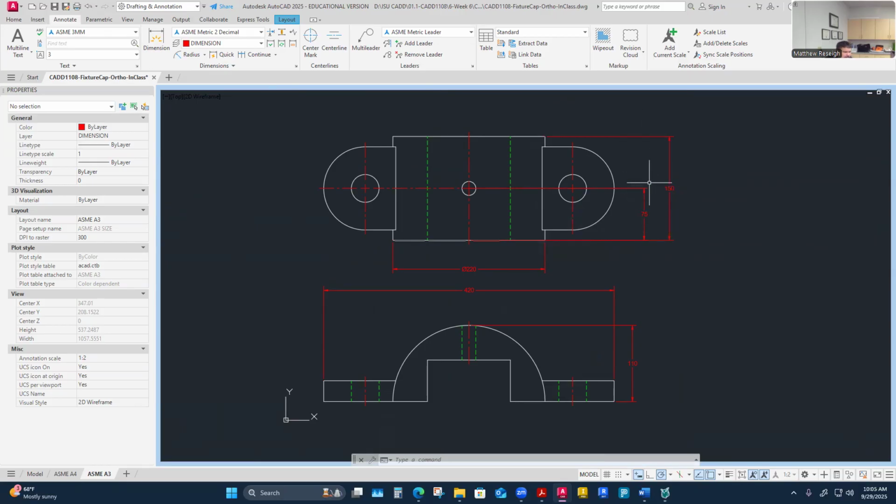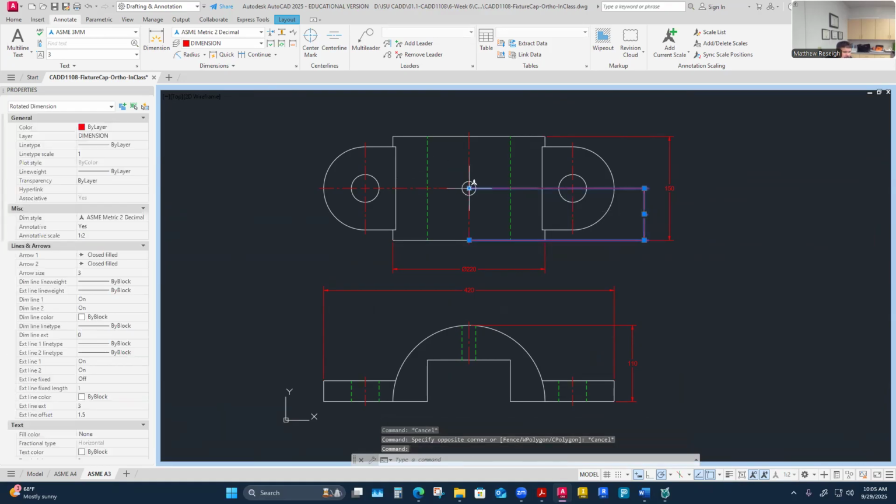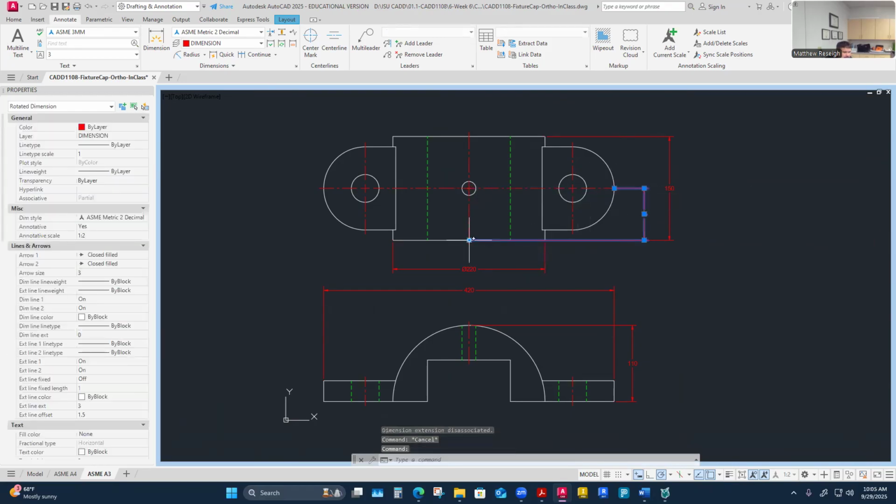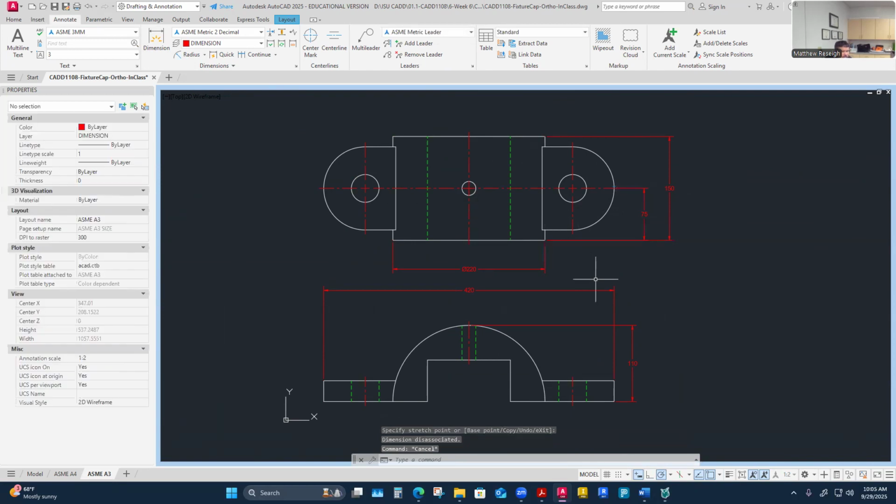That would be kind of maybe redundant. These two work together to give a size and location now. And I just need to pull those extension lines back to the object edge though. So this one here, that's kind of what I'm referencing in reality, that's the part, but I'm going to pull it back to the object edge like this. And so it's 75. And I haven't cleaned these up yet. I'm just pulling them. So that's 75.